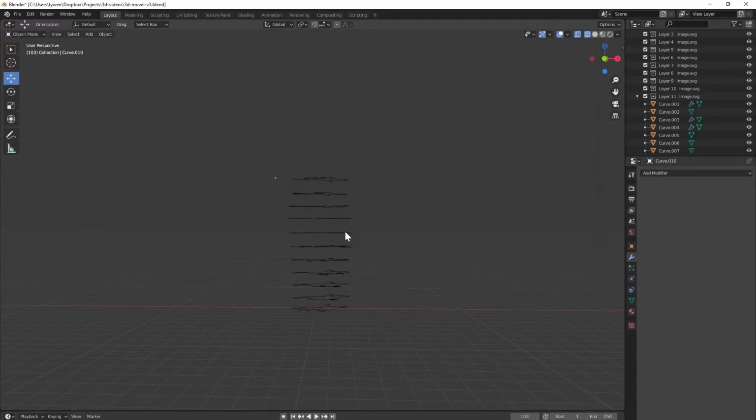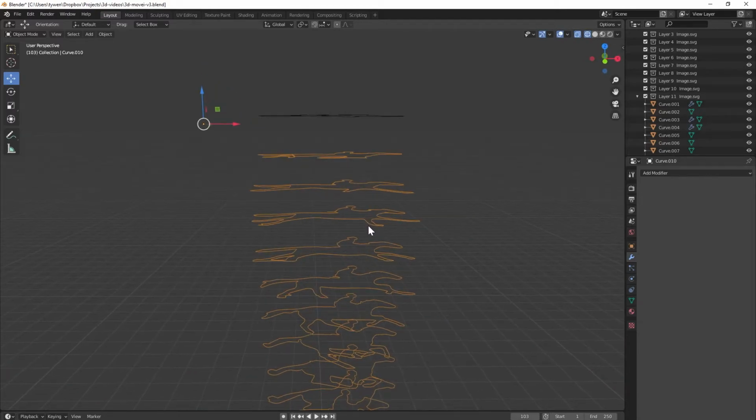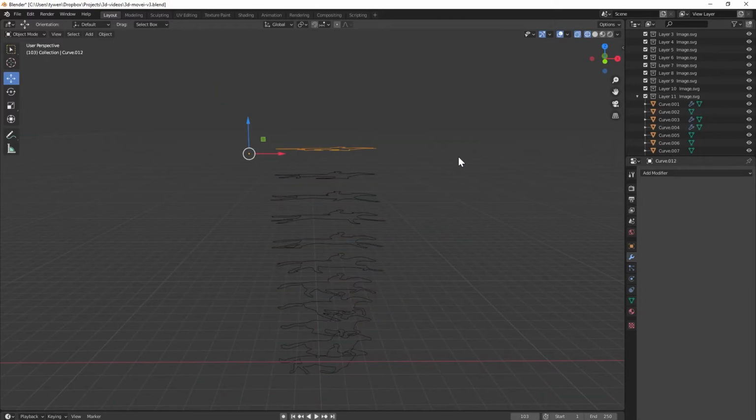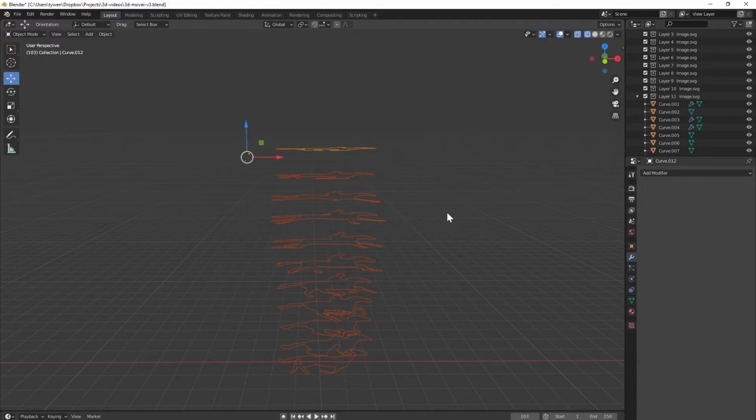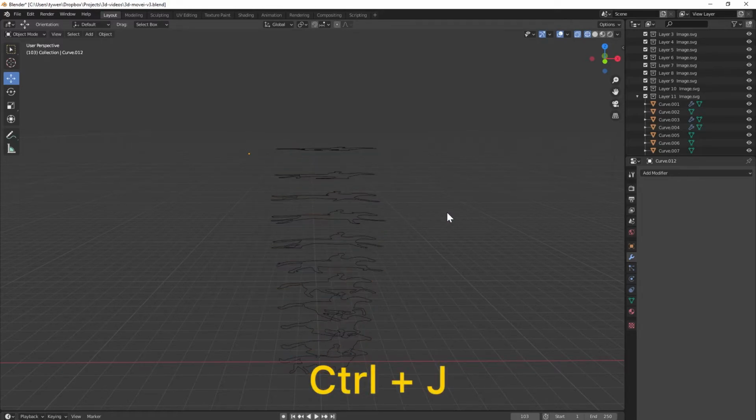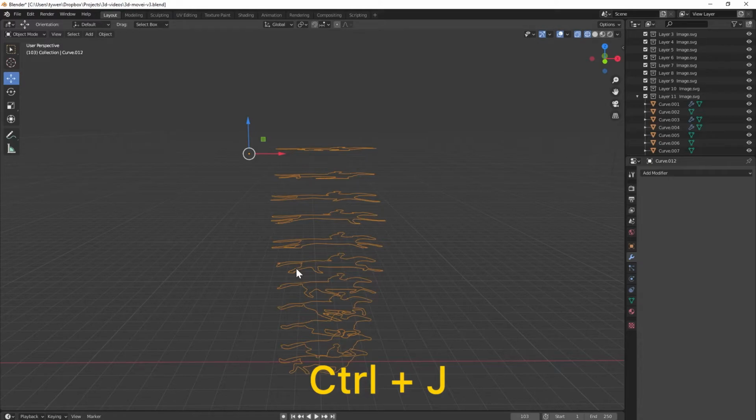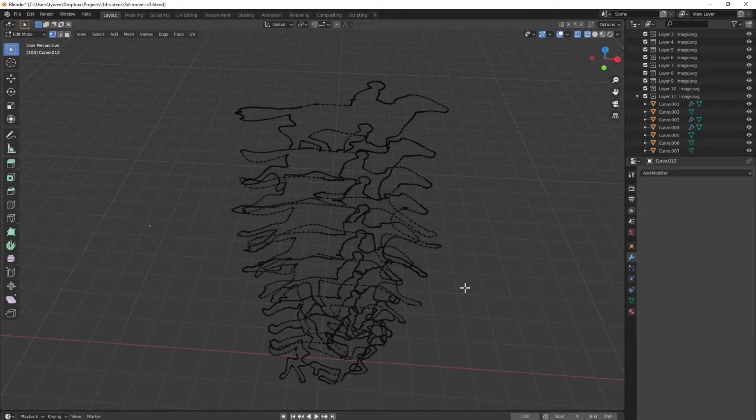You'll notice that if I select this pillar, all the objects are highlighted. If I select this one, only that one's highlighted. That's because this object is not part of this object. To make them all the same object, which is what we'll need later, we have to select them both and then do the shortcut Command J. The manipulation we're about to put onto the mesh requires that they all be in the same object because we have to enter edit mode by pressing Tab.